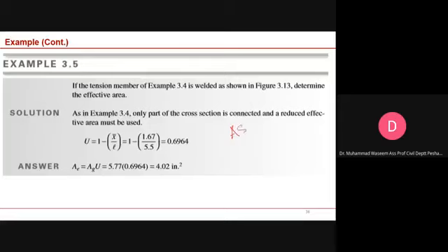For example, for ASD, so that you remember, you will use A gross, and for fracture you are going to use Ae Fe. You have calculated Ae in this example. Okay, so I would suggest that you always use this, and you should start using your manual.